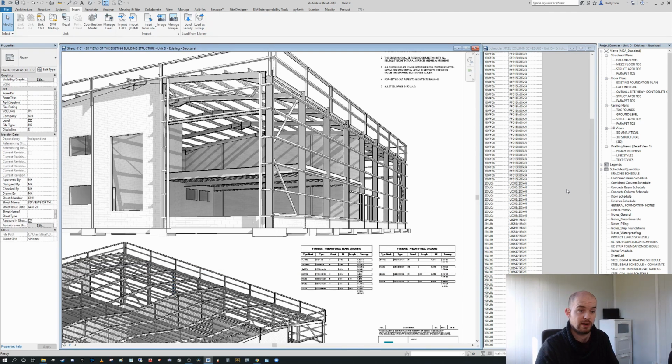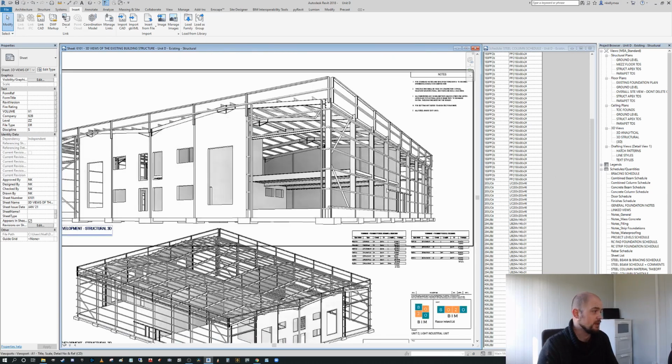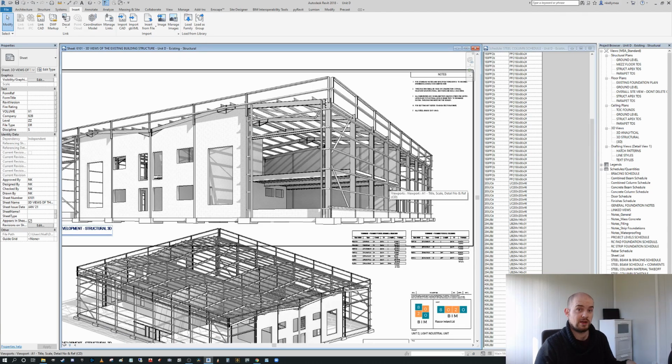It's very useful, and I recommend if you're doing a lot of scheduling in your projects, depending on the scale of them, you should schedule for automatic reasons to save you time and grief in Revit anyway. But if you have very large projects and it becomes difficult to identify things, I can't recommend this method of selection enough. It's very, very powerful across a project. So that was number 14, how to select relevant Revit elements directly from the schedules.